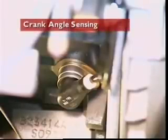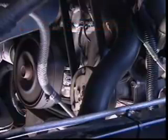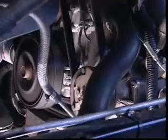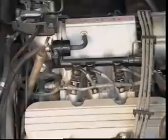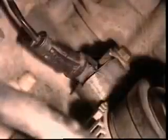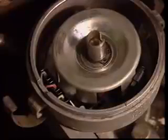This section examines crank angle sensing. Crank angle sensing uses information on the speed and position of the crankshaft to control ignition timing and injection sequencing. The control unit can then trigger the ignition and injection to suit operating conditions. The position sensor may be mounted externally on the crankcase wall, or it may be inside the housing of the ignition distributor.